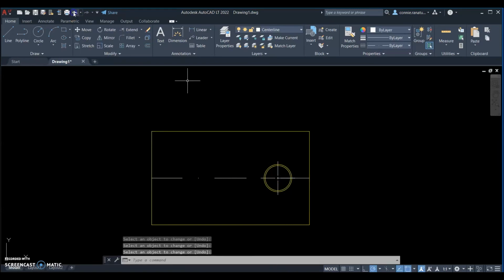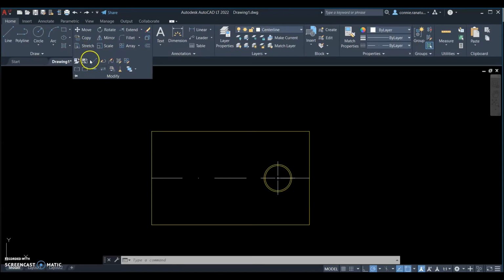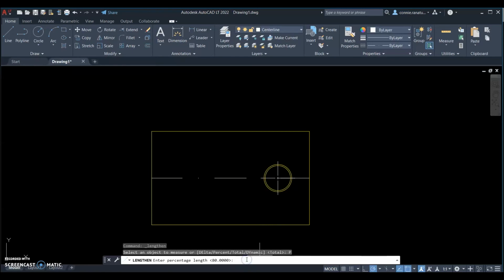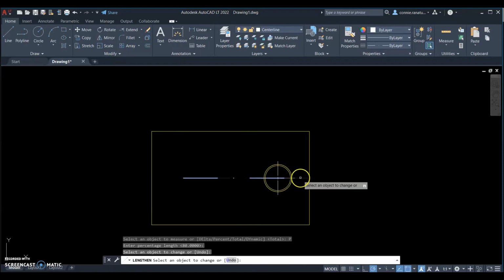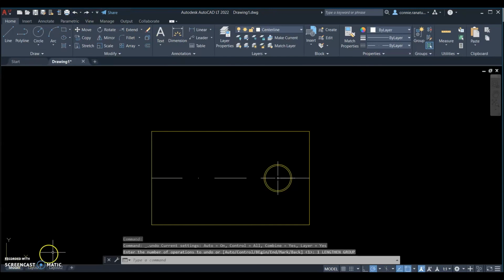So if I do regret on that, I go up to the Lengthen Tool again. I choose %. And I like to have this 80%. So I write 80. And then you see it will cut the line with 20%. So I do regret on that one again.